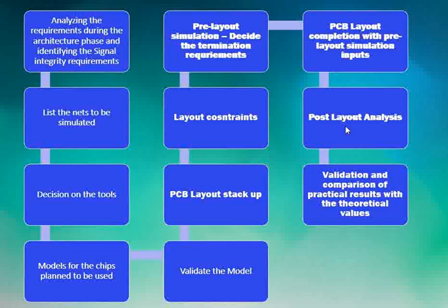He should also follow up on the kind of testing that is being done on the PCB, and always look towards capturing the waveforms and comparing the timing related aspects with the simulation results, and see how closely they are matching.